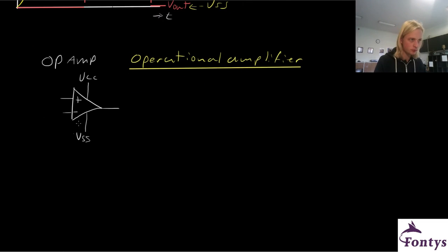If we look at this, the names are quite similar as well, because this is Vout, the output voltage, and this is the positive input, or Vin plus, or however you like to write it. And this is the negative input, Vin minus. So if you want to use an op-amp as a comparator, it's very easy, because an op-amp is a very small and easy to use amplifier, which amplifies the difference between these two nodes with an amplification of like 1,000 or 10,000, a very high factor.